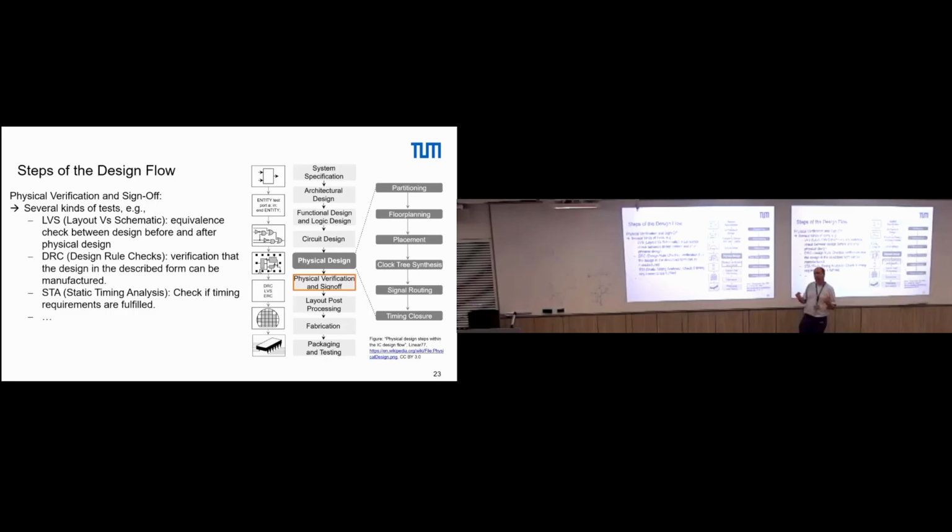Timing properties we will discuss a little bit later. To find out if something like this happens, you do static timing analysis today, sometimes statistical static timing analysis, but mostly static timing analysis, which really checks under specific simulated conditions. So for specific temperature conditions, for too low or too high voltage, how does your circuit behave? Does it fulfill all the constraints that you put?